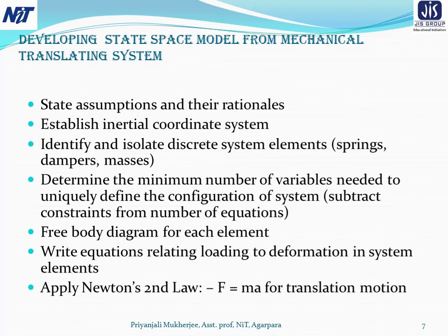Generally, first we need to know what the physical variable form is. First we need to describe the control system by formulating the equations that describe the dynamics of the control system. Then we select the state variables, and one method is to choose the physical variables associated with energy as the state variables. The number of state variables may be equal to the number of energy storing elements in the control system.